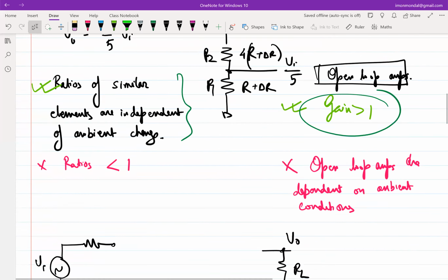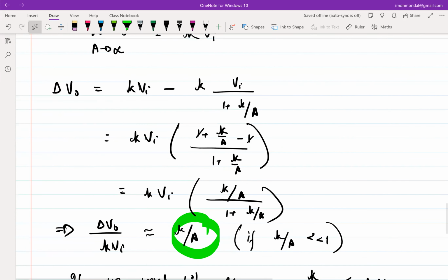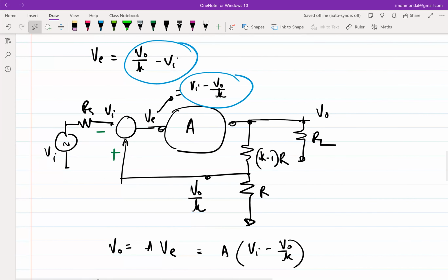So in this case, if we use the same analogy, we need to see whether the sign of the loop is fine. If we are not aware of the sign of the loop in the first place, we have to have some mental test to figure out whether the sign is fine or not, right? So what is the mental test? In a negative feedback loop, the loop action should always be to negate an excitation in the loop, right? That is the main core principle.